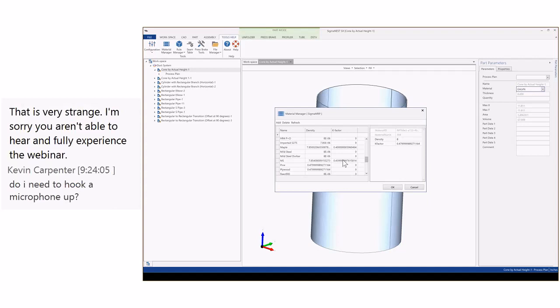It also is possible to use a fixed K factor for all parts if you're using really thin material where maybe that is less of an important thing to manage per material, if you want.